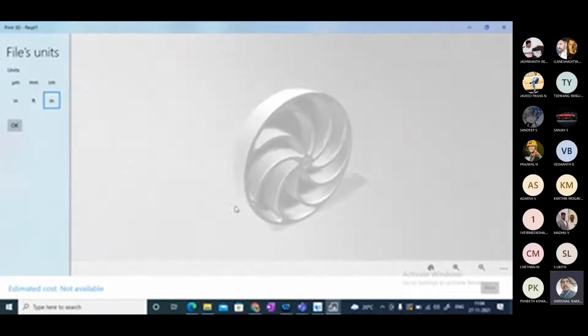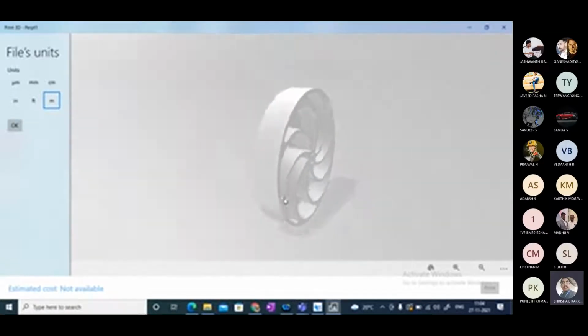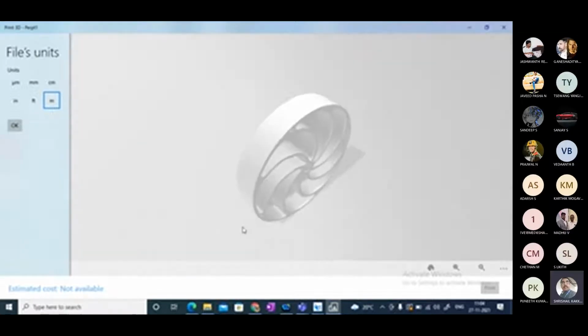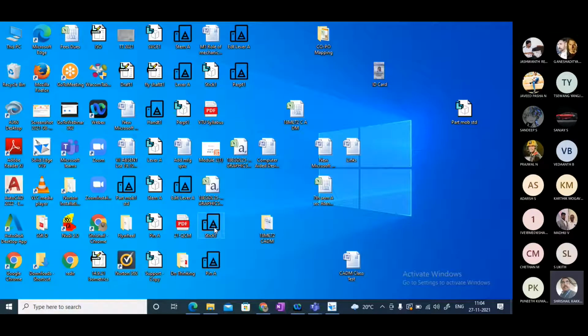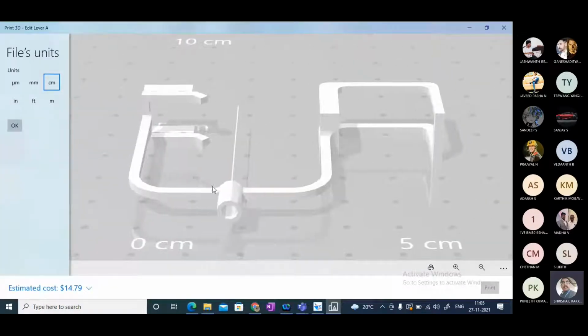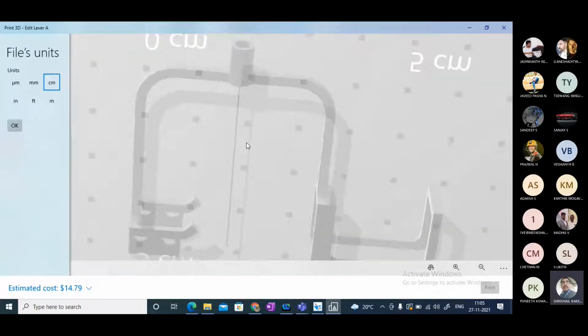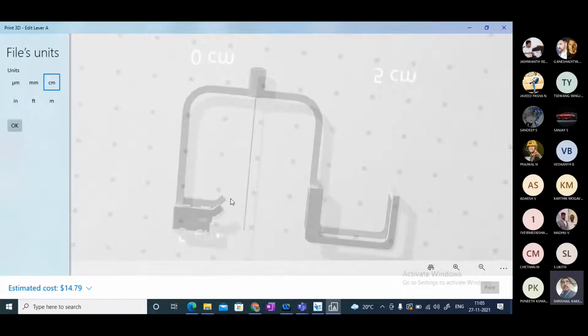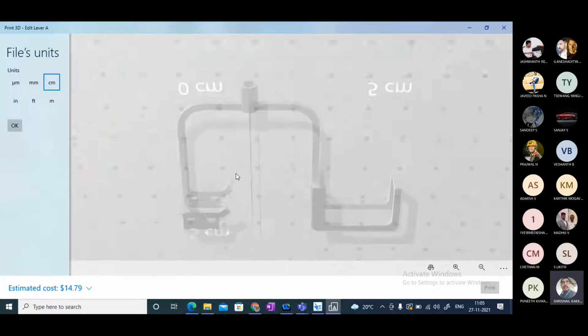Now, this is the STL format, and this we are going to take. Before we get into this STL model, how does the model have to be kept? Whether like this or like this, whatever the method is. One problem I'll be showing you. We had a small problem earlier. You can see this particular stick we have created, and we have to keep this model like this, because in between it cannot take this material adding process. Some supports we have to give.